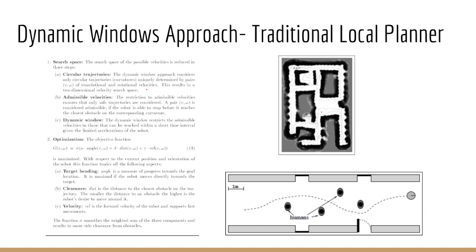To meet our purposes, we needed a planner that can help us plan, avoid obstacles, and do it quite quickly. For our purposes, we don't need to find a global trajectory since we guaranteed there's a global trajectory in a racetrack. And so we only need a local planner, which in our case consistently avoids obstacles that might be new to the environment, which is why we chose DWA.